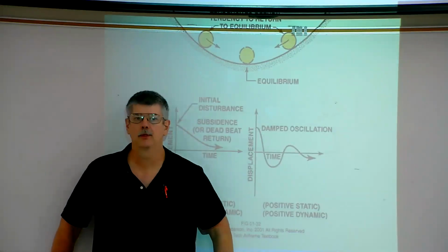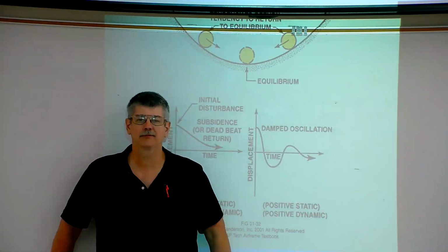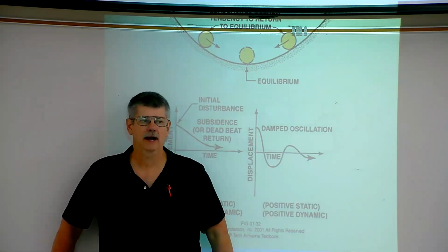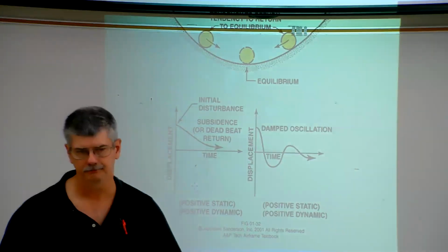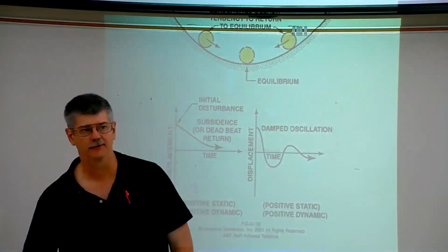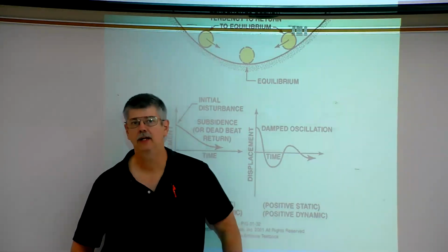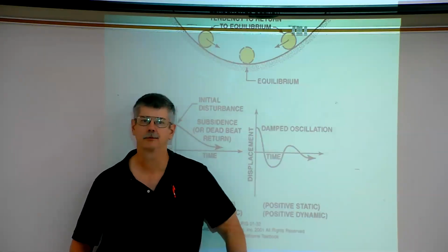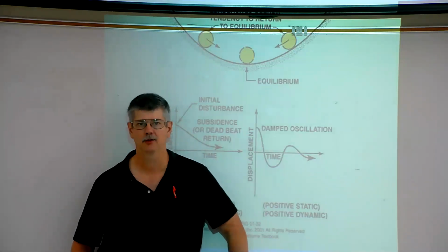There's a problem though with this arrangement, and that is when the right aileron goes down, producing more lift, it also produces more what's called induced drag. And the aircraft has a tendency to yaw in the opposite direction of the roll. This is known as adverse yaw. Because they needed to minimize adverse yaw, an aircraft may have one of three different ways that the engineers figured out how to minimize adverse yaw.